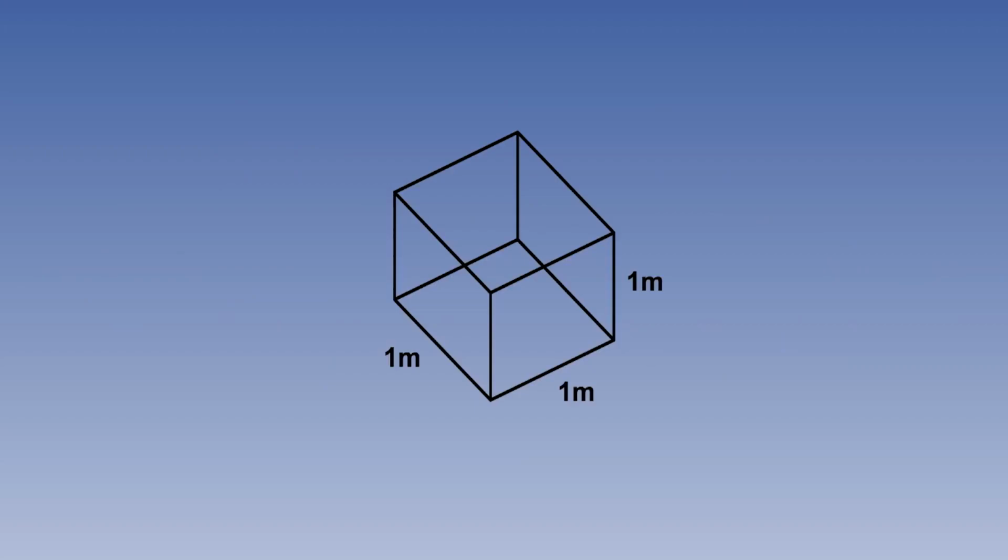Let us consider the kinetic energy of 1 cubic metre of air moving at a stated speed. It is the product of the local air density, ρ, and the square of the speed in metres per second, divided by 2.